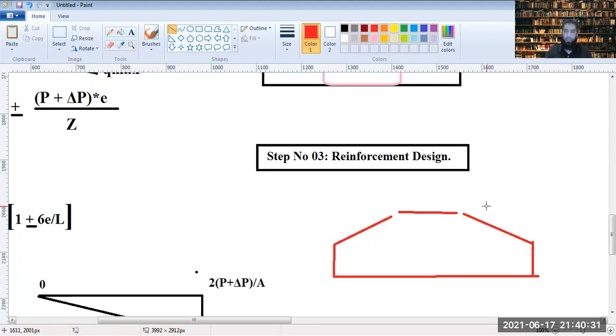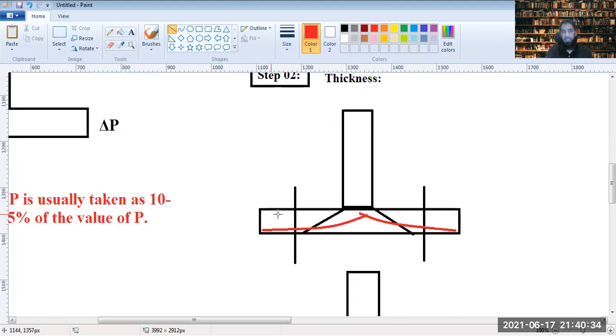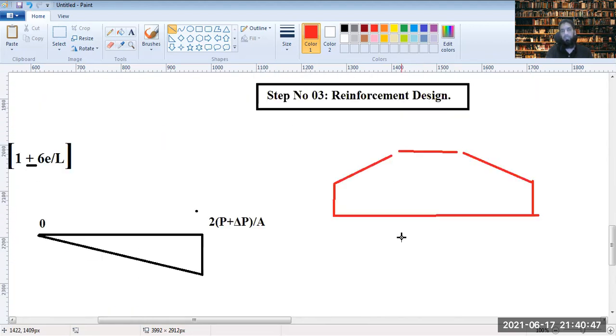And now, why do we require this? Because just now I showed you that there are little tensile forces and little shear transfer, little moments generated at the top of this. So this is not contributing much to the overall transfer of the load. Thereby, we can have a tapered footing so as to achieve the economy of the isolated footing. So we can go for an alternative design of a tapered footing as well, and that saves our cost. So now we'll be taking up the design example for design of the isolated footings.